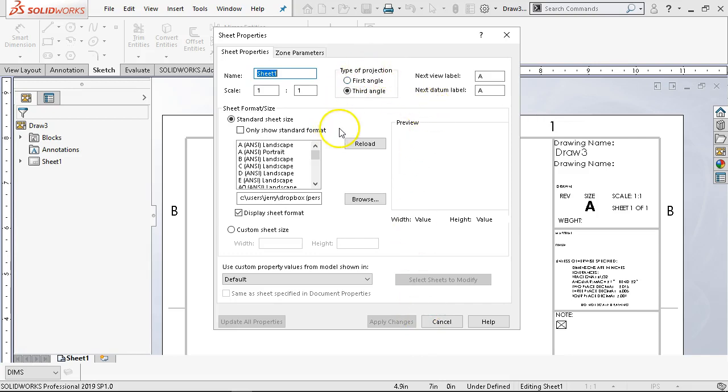So a couple of things since we're on this page, just in relation to drawings, you can rename the sheet. If I have a drawing package that I know is going to approach 10 sheets, 20 sheets, somewhere in there, I will change the name to S1 instead of sheet 1, and all of the little tabs going across the screen have a better chance of being able to select those and not overrunning the edge. But most of the time it can stay as a sheet.